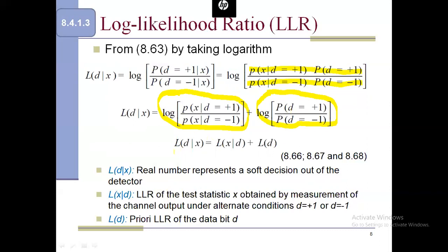So in fact, we have the term as the log likelihood of the posteriori probability, which will be the log of the channel stats into the log of the priori probability of the data.